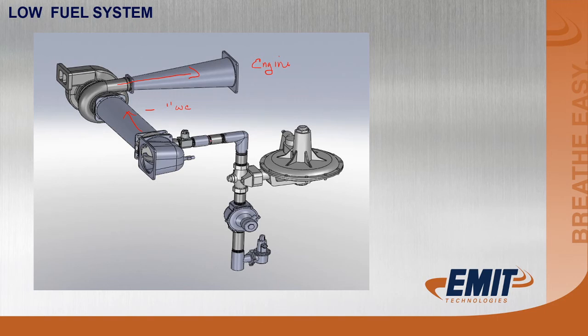Now this is really common. You'll see this on Caterpillar gensets. You'll see this on 3516 Caterpillars with twin carburetors on them or dual carburetors. You'll see this on CG 137s, -8s, and -12s. Low pressure fuel systems were originally designed to operate on utility natural gas, where they had a low pressure rating for a building, say a standby generator for a building or apartment complex or office building would be supplied with utility natural gas. And that utility natural gas is usually between 2 to 4 psi coming into this.